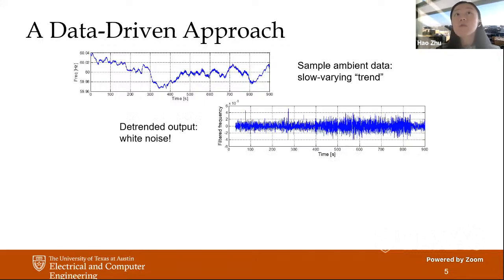With that, what we get is this white noise. After this filter, we can see this white noise type of signal. This is actually what captures the dynamic behavior of the grid. It is almost like thermal noise, where you cannot see much pattern. This makes the everyday data uninteresting, but what we are going to show is that it is useful for recovering the large disturbance behavior.